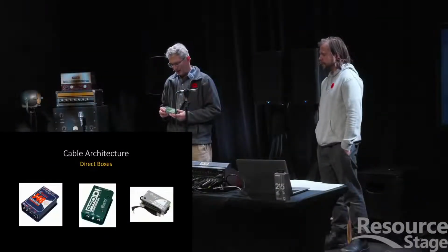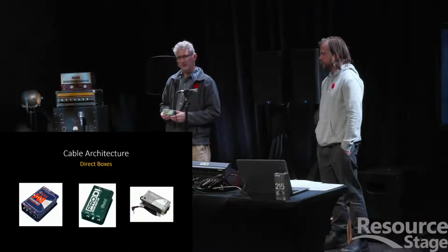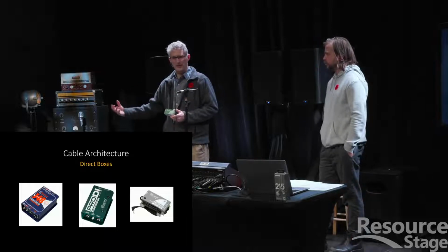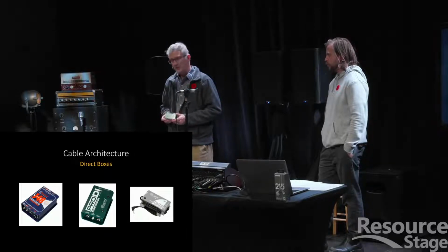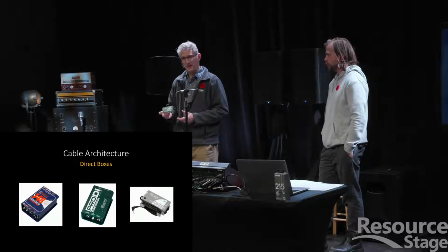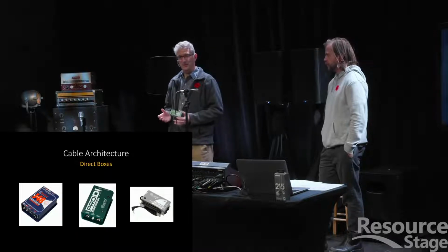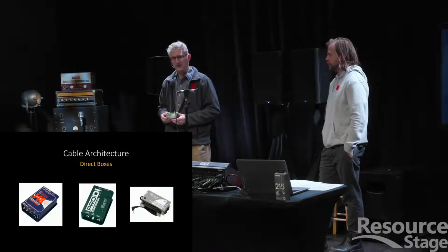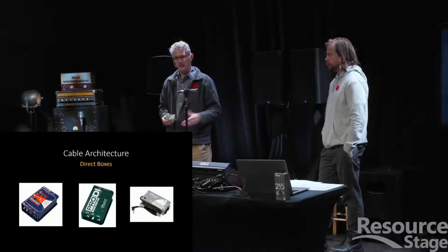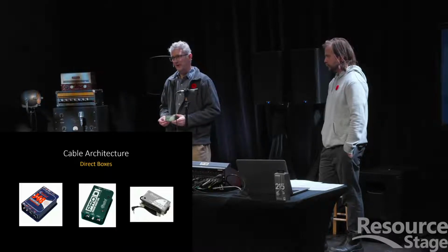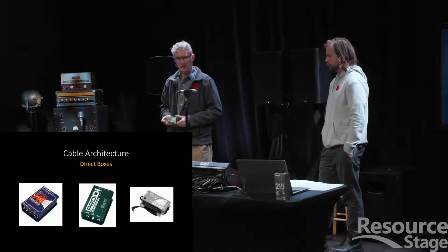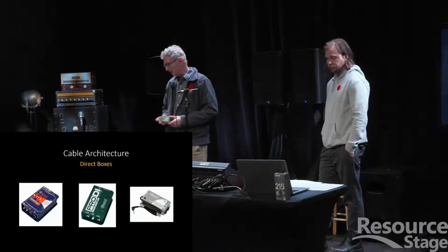And so if you plug in an instrument on one end and connect it to your microphone and you get a buzz or a hum or something, the first thing that you want to do is press your ground lift button on that particular instrument and see if it goes away. What that does is it breaks the shield or the grounding connection between the instrument and the mixer, and that will often solve that problem of a hum or a buzz.